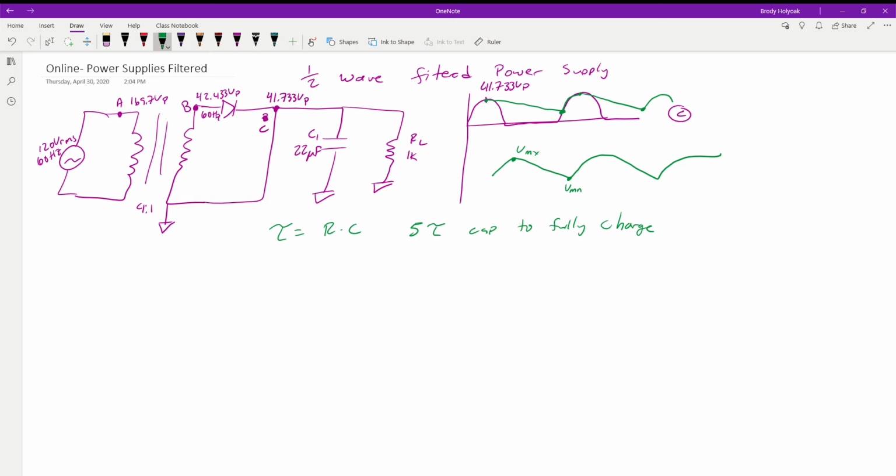So the first thing we look at is what is the V minimum. We're going to use the instantaneous voltage equation to solve for it. So the minimum voltage is going to be equal to the final voltage that our cap is trying to get to, VF minus VI. So again, we have V final minus V initial times e to the negative t over tau.